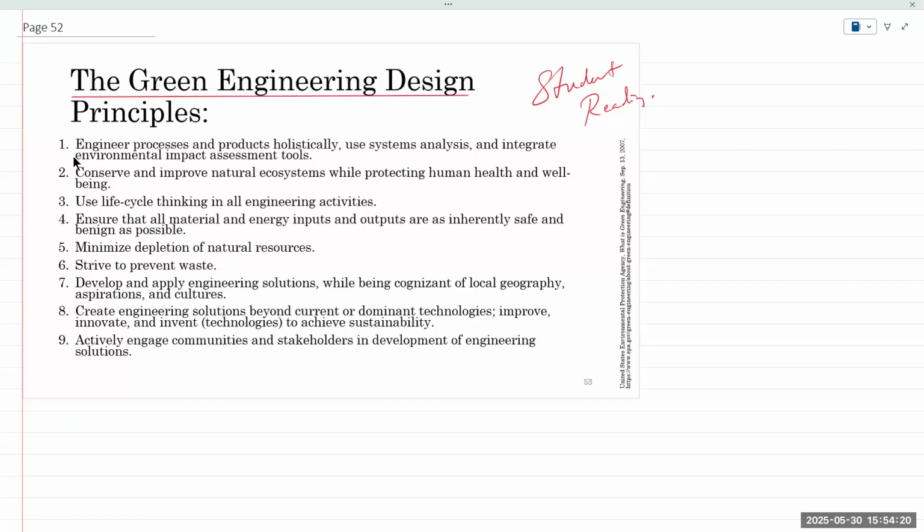We'll have a quiz on Monday based on Thevenin Norton. Again, Thevenin Norton, no analysis, but just how to set up the circuit in order to actually perform Thevenin and Norton analysis. And that's what I'll be assessing on. So it'll be rather straightforward. Setting up the circuit simply means, how do I modify the circuit in order to determine Thevenin resistance? How do I modify the circuit to determine Thevenin voltage? How do I modify the circuit or set up the circuit to determine Norton current? That's it.